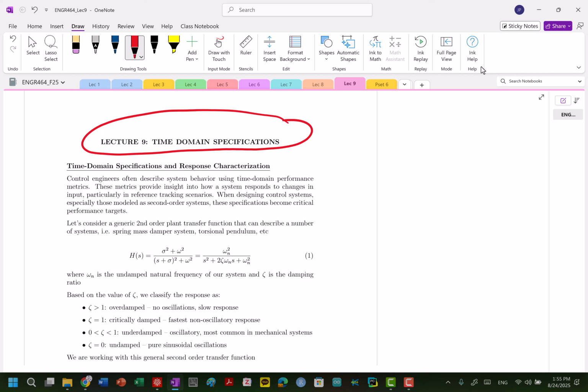And we've started to see that if we tune the poles of our transfer function of our system, of our plant, or of our controller, whatever, I mean, we're getting a little ahead of ourselves, but we see that we can tune the poles and the zeros of our system in order to change essentially the response of that system. Now, we need to start to think about how are we going to analyze what are the numerical metrics, what are the specifications that we need to hit for a specific design.